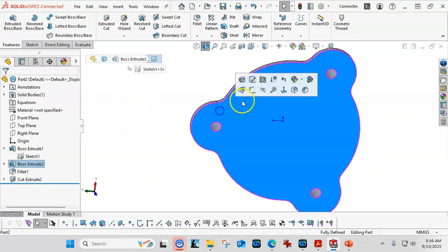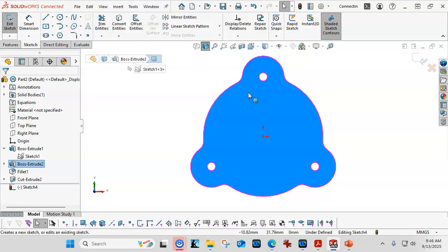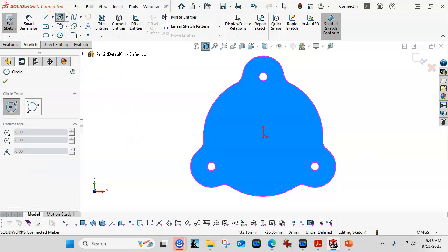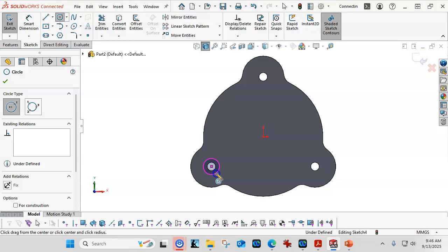All right, on the back side then, or top side, whichever way we're looking at this, we're going to do the sketch. We'll go back in and pick up our radius of 6, diameter of 12. And I'm just hovering over the circle to where I see those center points.